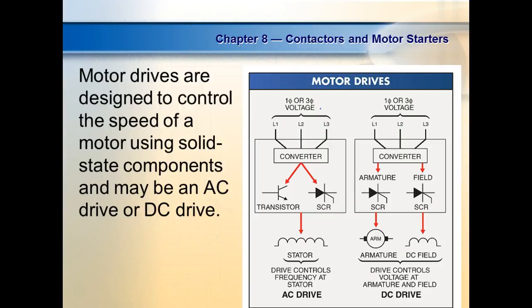If you lower the voltage, what does the motor speed do? If you lose any field voltage on a compound motor or a shunt motor, that sucker can run away on you if it's up and running. It could swing itself apart. So normally what we do is we control the armature voltage, because if we raise the voltage, the motor speeds up. If we lower the voltage, the motor slows down.